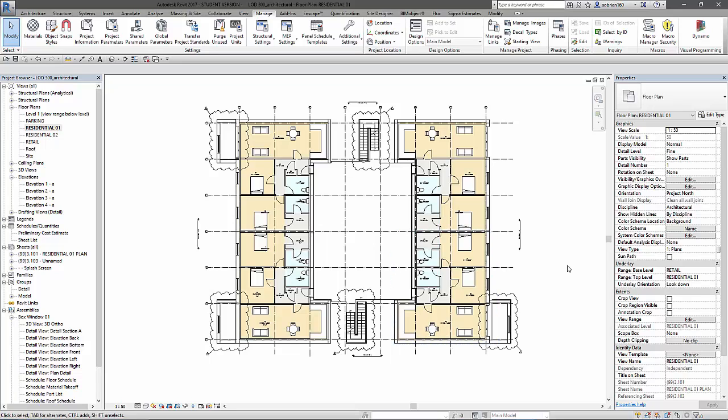but often you might want to timeline other elements of the model in a different kind of way. But the important thing is that we've now set up a parameter for the project, which means that every element of the project has a four-dimensional parameter that we can then come back and modify, or we can attach to a timeliner in Navisworks by using automatic rule attachments.